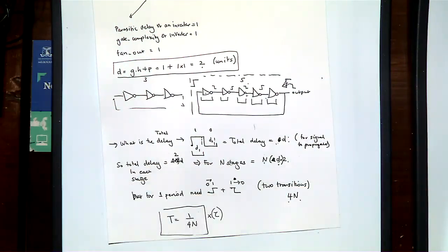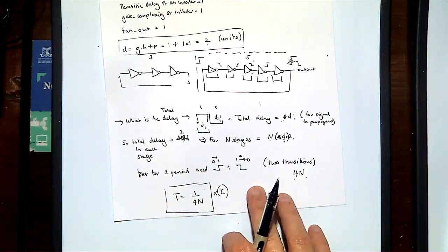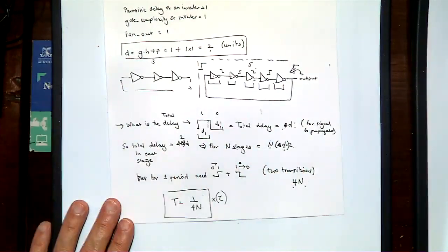So you can start building some very interesting ring oscillators very quickly, and you can approximate very quickly what you would expect the frequency of oscillation to be. You can also use this to work out your doping profiles and which corner you are on a particular chip. What I would suggest is that you go home and look at skews, or process skews.